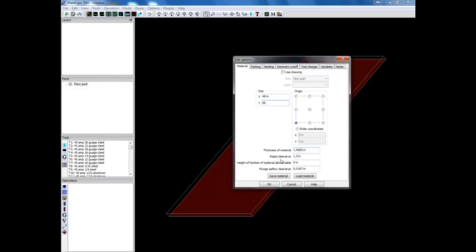Next you're going to set your rapid height. You're going to make sure your rapid height is set to 1.5 inches. By default it'll be much lower. This rapid height is how high off the table the machine transfers in between cuts. I find 1.5 clears most tip-ups. If you wanted to, you can make it bigger. Once you're done with that, you click OK. Next, you go back up to Options, and you go down to Machine.